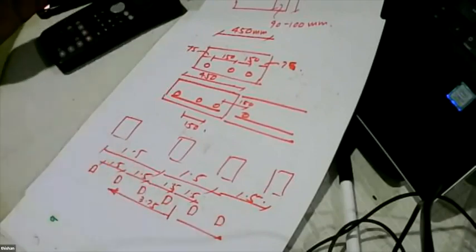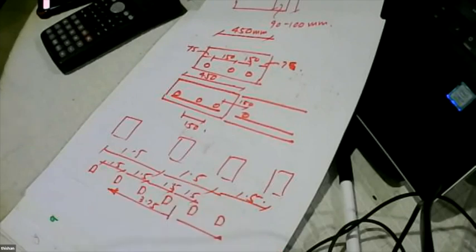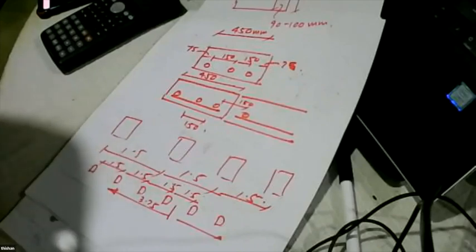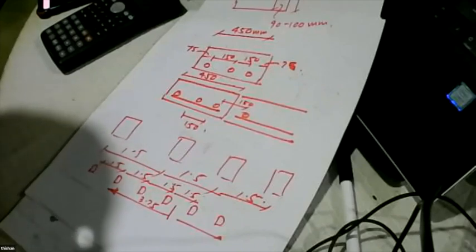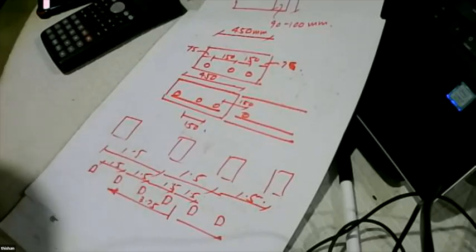So don't make them too big, not too wide, not too long, because we have to make sure there are adequate number of structural beams to transfer the loads onto the two supporting members, maybe two abutments or an abutment and a pier. Because of this reason, we generally like to see a spacing of about 1.5 meters maximum. Is that clear?